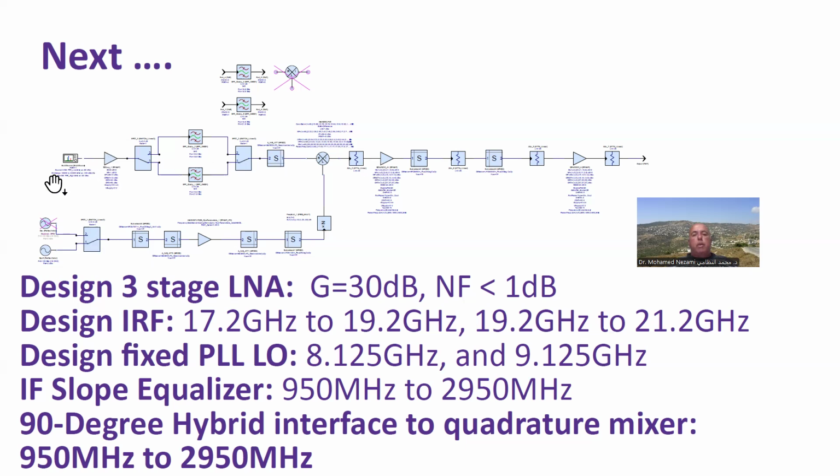And there's got to be a command that comes in and tells this LNB to switch over to either low band or high band. Currently, commercially, the cheap ones for home devices, home DirecTV, use the DC supply that comes in here, which can vary from like 18 volts to 15 volts.